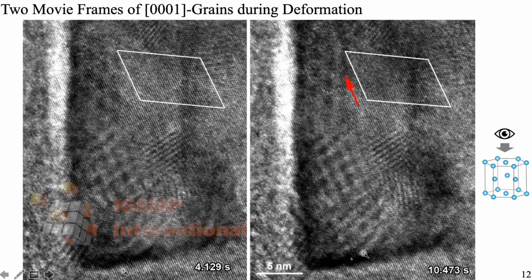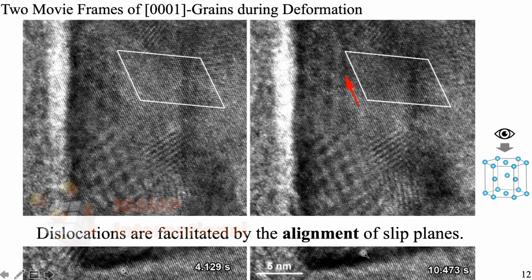And then the grain boundaries actually move much less if the sides of the grains all have the cross slip system passing through the grain boundaries. So that supports the idea that the alignment of the slip system, which corresponds to the dislocations, and these two different deformation modes cooperate, and then eventually give you the final property of your materials.